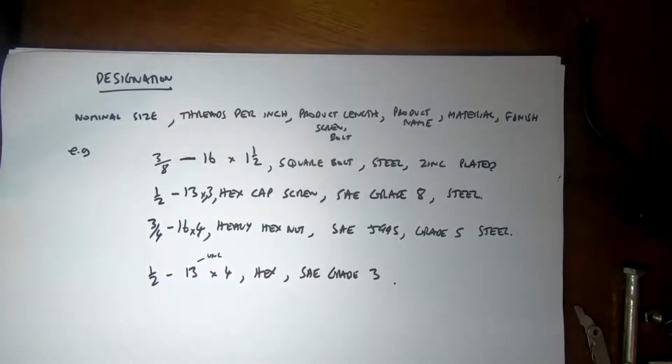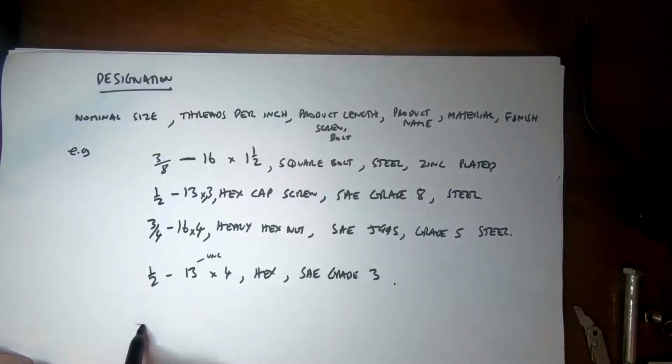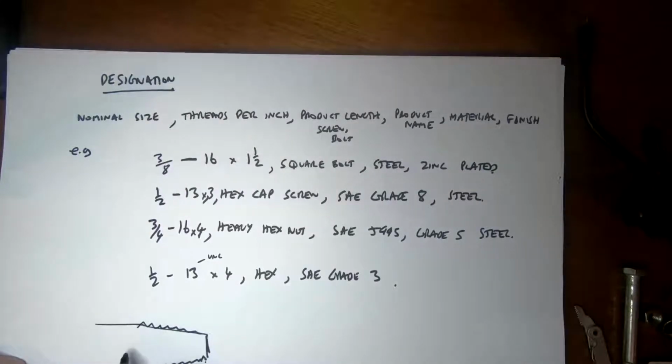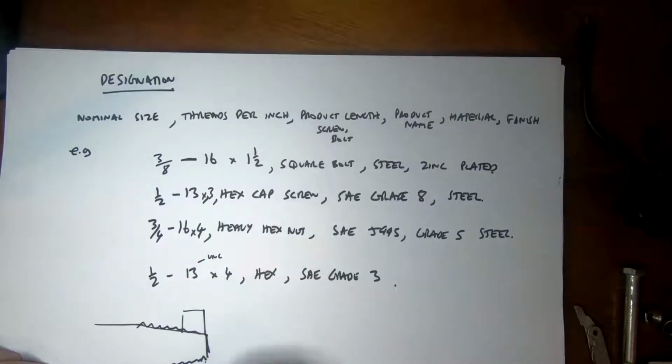There are a whole bunch of other standards. One of the ones I've been using is the pipe thread dimensions. The pipe threads are actually kind of interesting because the thread actually on the end of the bolt, if you will, exaggerated it here, is tapered. And the idea then is that as the nut comes on, the diameter increases, so you actually lock it into place and seal. So this would be your pipe thread. So that's a really useful one that I've found as well.